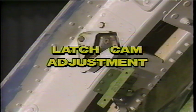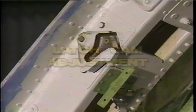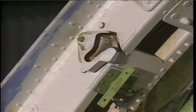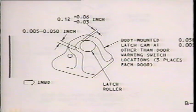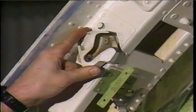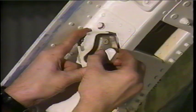The next adjustment is to the 4 latch cams. The objectives are to obtain exterior skin flushness requirements and to prevent the roller from bottoming out on the body-mounted cam. First, check skin flushness to determine if any adjustment is necessary. Initially, locate the 4 latch cams so that the index hole in the cam will align with the index hole in the frame. Adjust the body-mounted latch cam on the serrated plates as needed to meet fair requirements at the top, bottom, and sides of the door.